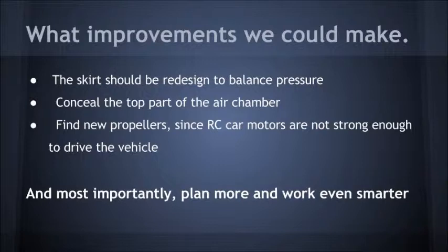To fix our skirt, we would redesign it and create a more balanced system of pressure. We would then have to increase the effectiveness of our lift motor, which we would do by concealing more of the open area above the lift propeller. Thirdly, to improve our hovercraft, we would need to find a more powerful propeller because RC car motors are not strong enough to drive our hovercraft.